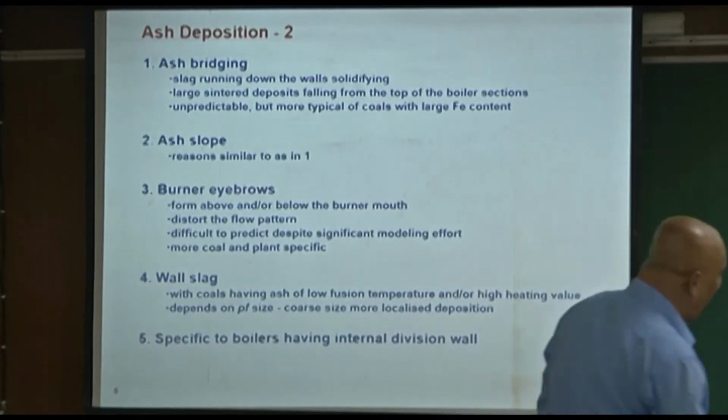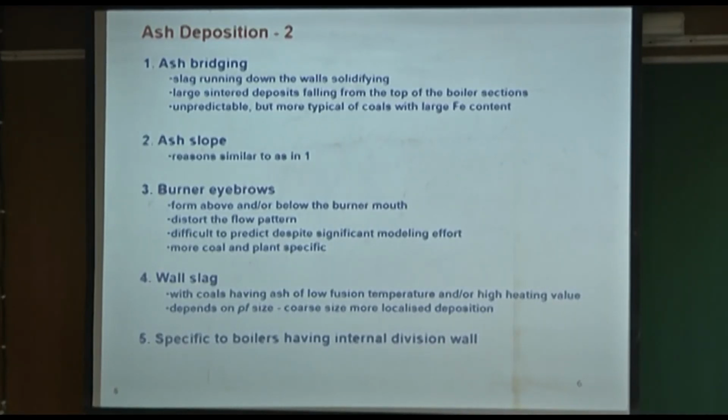But small amounts of calcium oxide, sodium compounds, and Fe2O3, which I forgot to write completely, lower the sintering temperature and the melting temperature very much. So these are the ones which create the majority of the problems: the sodium, the calcium, the magnesium, and the iron. And to a lesser extent, phosphorus also creates problems if it is present.